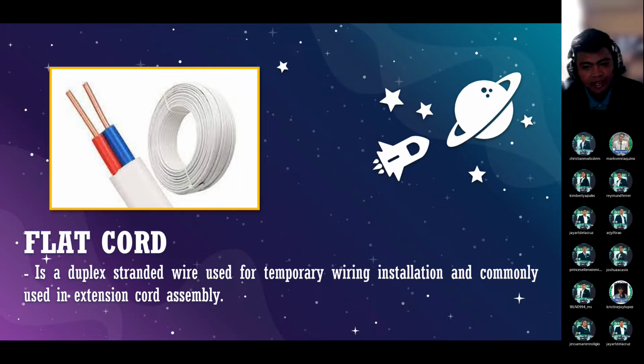So, a flat cord is a cable made of round or rectangular, parallel copper wires arranged in a plane and laminated or molded into a ribbon of flexible insulating plastic. So, flat cord allows for compact designs for electrical conductors and tubings, encasing power, signal, video, data, and even pneumatic tubing in one flat profile. Is that clear? Yes, sir.